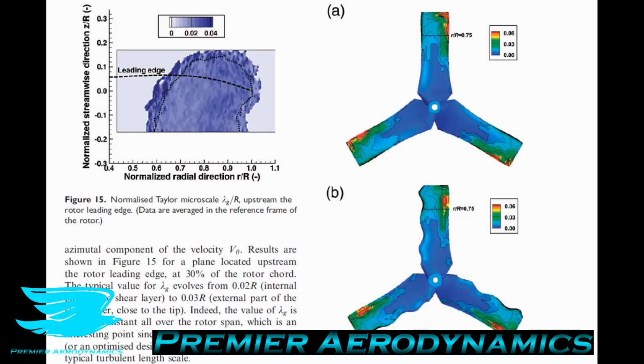One potential reason why, I'm not sure, I haven't investigated this particular bit, but I know about how tubercles work. One potential reason is that it's counteracting the circulation being produced over the airfoil and the wingtip vortex. So you can reduce the noise at the wingtip, I think, with this mechanism. Again, I haven't investigated this, so I'm not going to say for sure, but I think that's what's going on here. The third difference is the level of pressure fluctuations in the shifted blade geometry is reduced for two blades, the top shifted and the middle blade, and is increased for the last blade. Compared to the reference geometry, the shifted blade reduces pressure fluctuations at the leading edge, but it has detrimental impacts on the trailing edge noise.